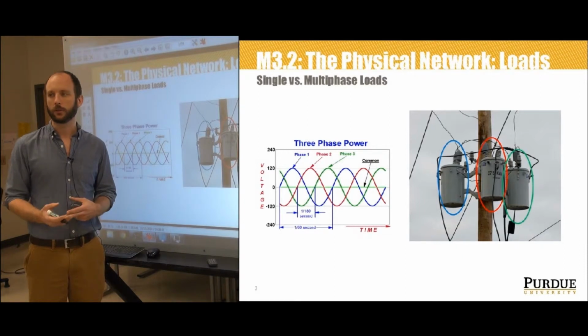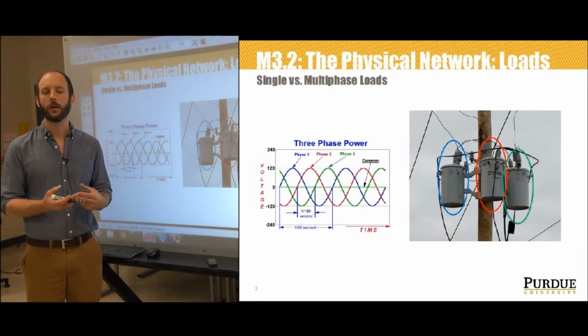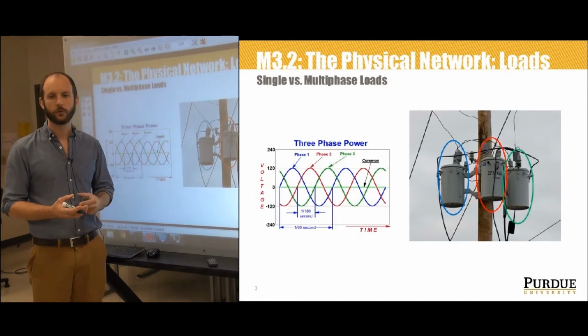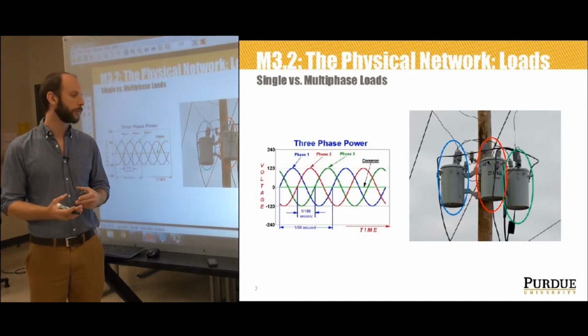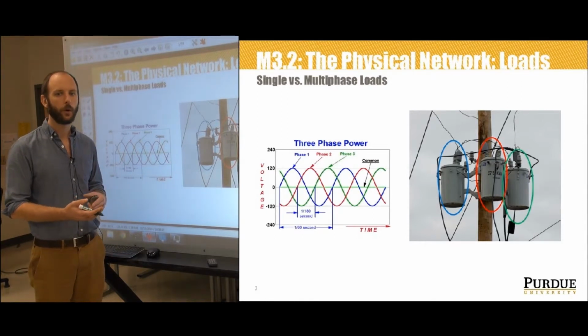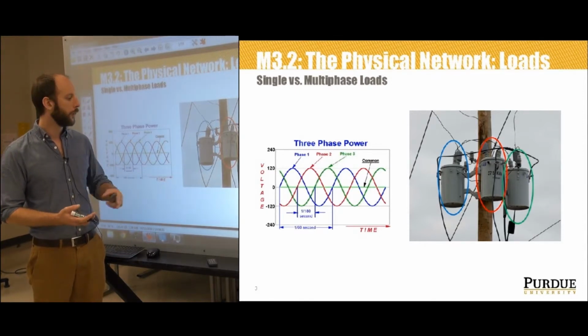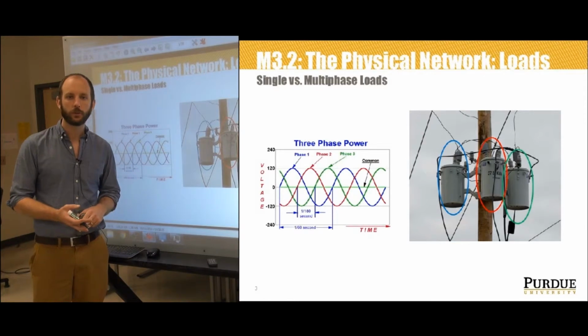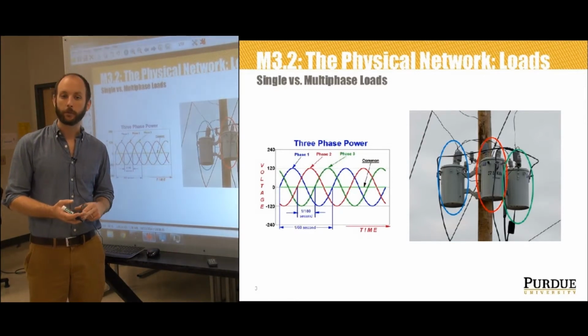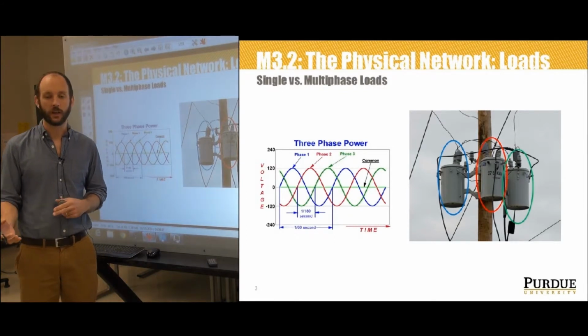This is such that you might find in a parking lot, in a neighborhood, feeding some customers, whether those are residential customers or commercial customers. But this is a pretty standard utility pole. This one's actually three independent single-phase transformers, each of these transformers being rated to an apparent power of 37.5 kVA.